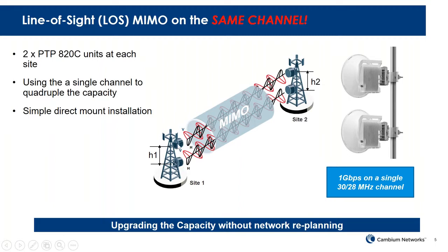So you see the first radio is beaming out 2 strings, V pole and H pole. That's using XPIC. And again, the second radio link is also another XPIC. But then to XPIC, using phase separation, you achieve 4x4 MIMO. The installation is a simple direct mount installation.